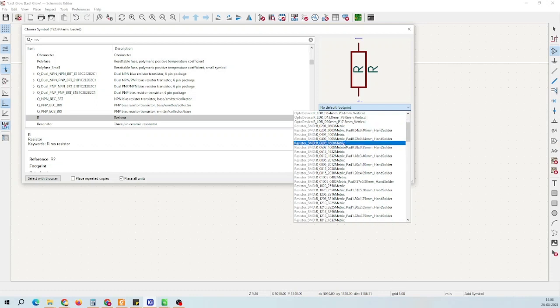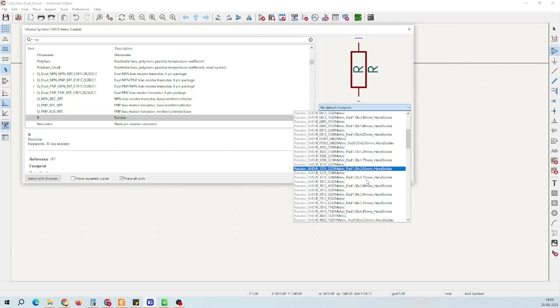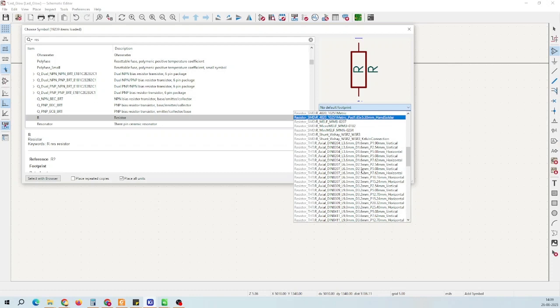Another way is, at this point of time it will be difficult for all of you to select a particular footprint, but I can list some of the footprints which are easily available and also heavily used in the industry. So that makes their availability in the local market easy. So here we are planning to use all through hole components only, no SMD components. Basically, components come in two footprints: SMD, which stands for surface mount device, and THT or through hole.